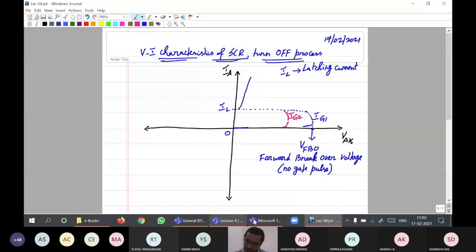Yes. So when we increase the gate current, the SCR begins to conduct earlier. Breakover happens earlier. Similarly, when you further increase the gate current, quite obviously, it will begin to conduct even earlier, IG3. So the relation is like this: IG1 is less than IG2, which is less than the third gate current IG3. This is the relation with regards to the gate currents.